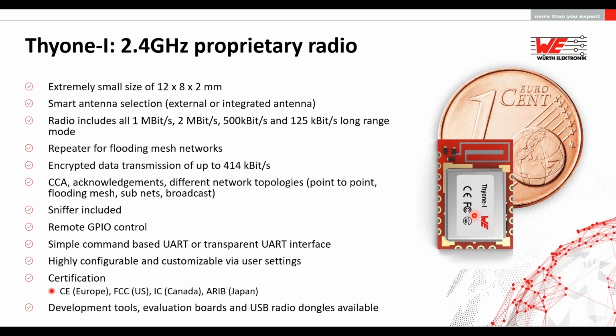It is really flexible in terms of physical layer with 4 different radio profiles, and supports flooding mesh. Most attractive probably for some kinds of applications would be a remote GPIO control. As you can see, the Thyone-I module has certain pins here. Of course, you have the standard UART interface and the antenna pins, but there are certain GPIO pins which can be configured using the radio interface. This is really interesting for some kinds of remote control applications.